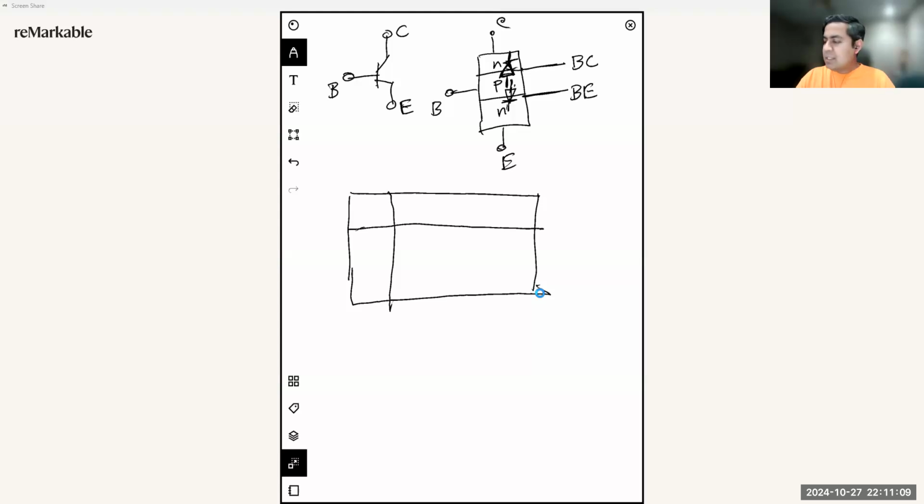You know when you form a PN junction diode or PN junction device, they usually form a space charge in the junction area, and then it creates a depletion region, which can increase or decrease depending on how we are externally putting a voltage across them. So in terms of operation, we can have them in reverse bias or in forward bias.